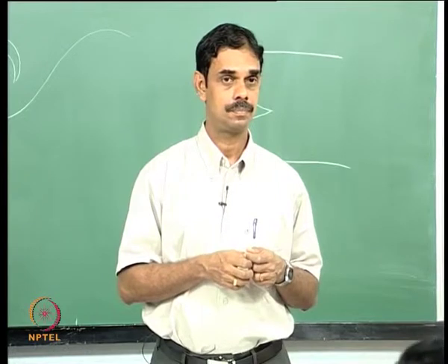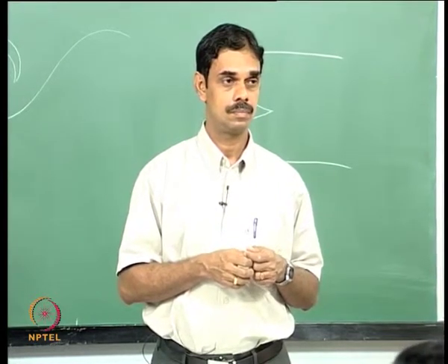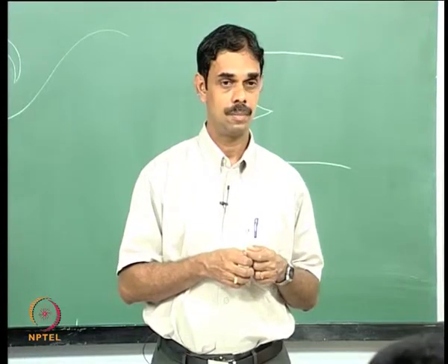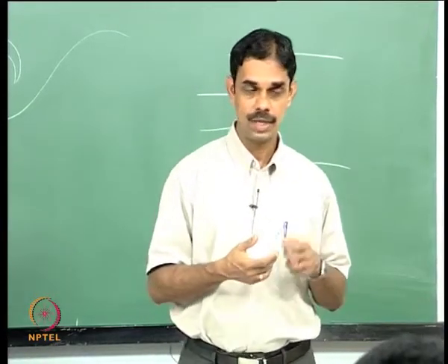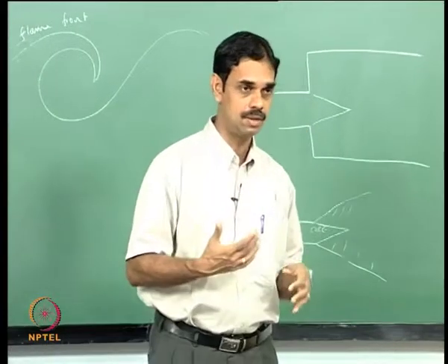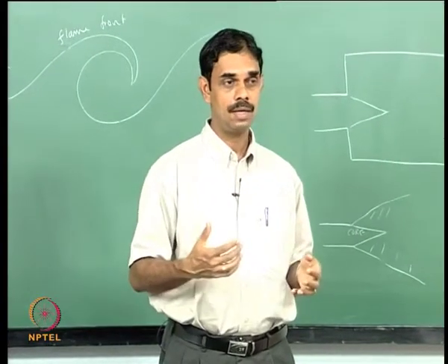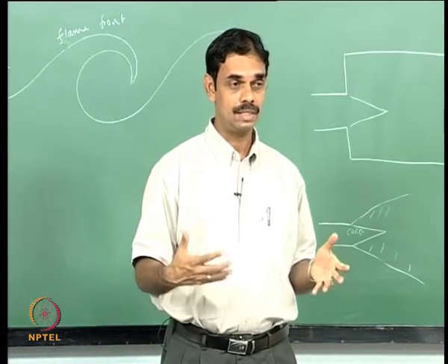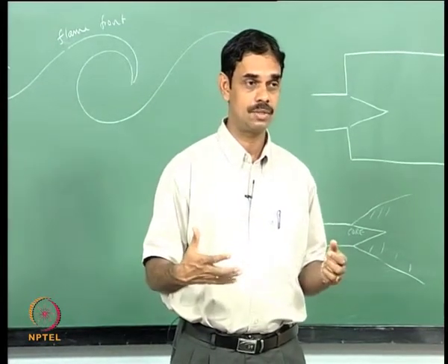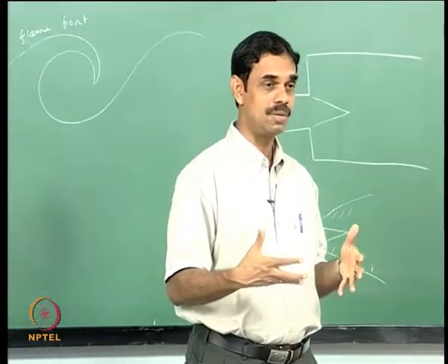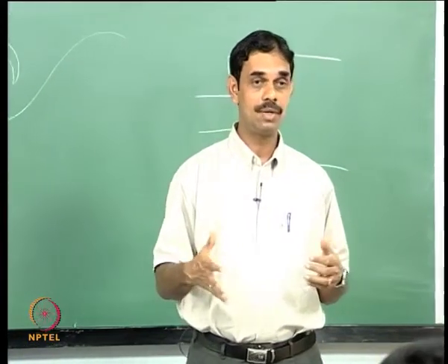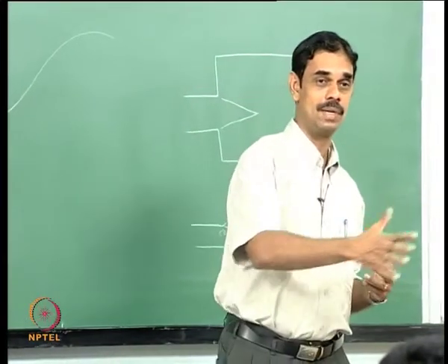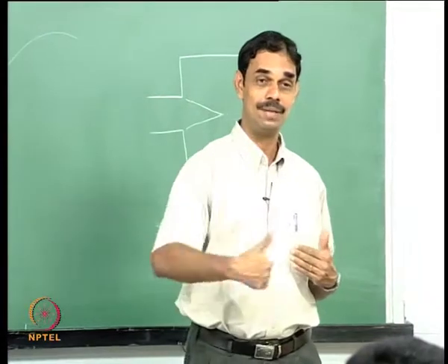So basically it's not the vortices formed inside that hold the flame in pulsating. No, the flame is being held by the recirculation zone. So we have to have a low velocity zone to have the recirculation zone. That is the purpose. We don't need a vortex to hold the flame, we need a low velocity zone. But we are also greedy, we want to pump in a lot of mass flow rate, so we want a high velocity stream coming in.